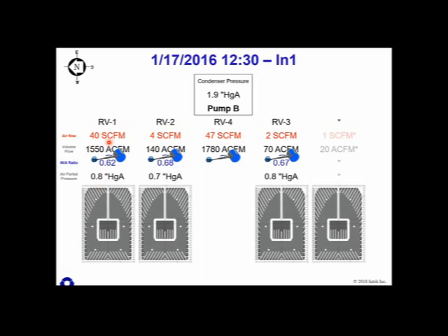If you just think of it as a hydraulic circuit, all these pipings, I don't draw it out here, but if you do draw it out, the hydraulic circuit will show you that the total flow will increase in this bundle and it will decrease in all of these bundles. If anybody wants me to go through that in more detail, I can. I didn't think it was important for this case study, but it's a very common occurrence that the total flow rate will be preferential to where the air leakage is coming from.